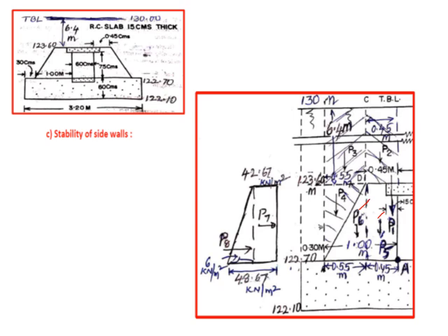So now we have to calculate what is the earth pressure. So earth pressure here is where intensity of earth pressure is Ka gamma into H. So what is H here, from here to here, which is 6.4 meters. What is Ka? 1 minus sin phi by 1 plus sin phi, that is 1 minus sin 30 by 1 plus sin 30, which comes to 1/3. So 1/3 into 6.4 into 20 gives 42.67.